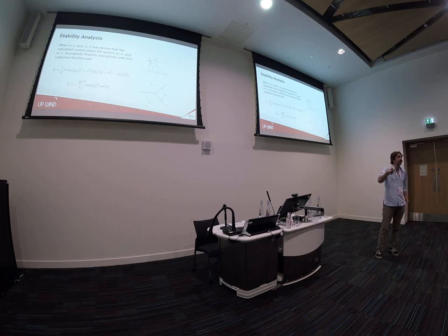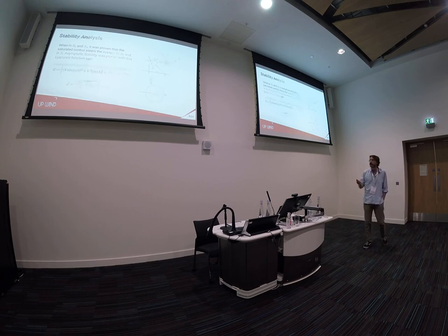If we can find that time derivative to be negative, we can prove that basically the guidance logic will always steer the kite or the system to zero, so basically to the path. Okay? That's the idea behind the Lyapunov stability analysis. And that's what we've proven.